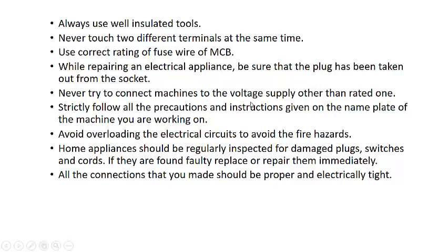Never try to connect a machine to a voltage supply other than the rated one, because machines or equipments have some voltage rating or other ratings. For example, if we have a toaster, it is usually rated for 220 volt. If we use 440 volt, it will get damaged. So we have to supply the machines the voltage for which they are designed or rated.